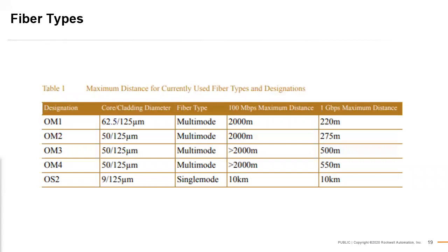You can mix and match your 50 micron fiber. It's always best to know what you're using there, but you're usually good enough. If you don't know if your fiber's an OM3 or OM4, if you were to use the wrong 50 micron patch cord, you're probably not going to screw up your system. It's going to work just fine. Yeah, so it's something to keep in mind and look at, but at the same time, it's probably not that big of a deal if you have the wrong one in this particular instance.